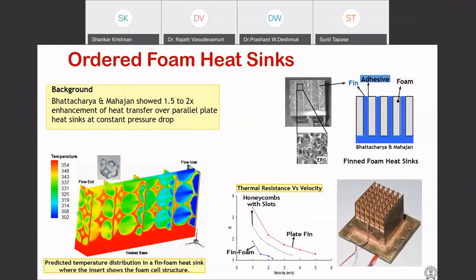So you have very high heat transfer coefficient happening at the pore level, and the conduction cross section of the ligaments is very small. That means its fin efficiency is going to drop dramatically. In fact, with some simple calculations you can estimate its fin efficiency, and you will find that on many occasions it falls well below 30%. That means we cannot make this heat travel only through these porous ligaments.